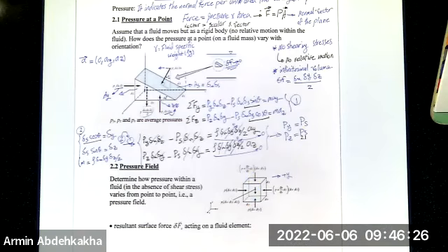What we are going to do here is ask: in the absence of shear stress, because we also consider that the flow is at rest, how does the pressure vary from point to point? That gives you the pressure field. So first, the flow is at rest, or there is no shear stress. And these are the pressures on each side.